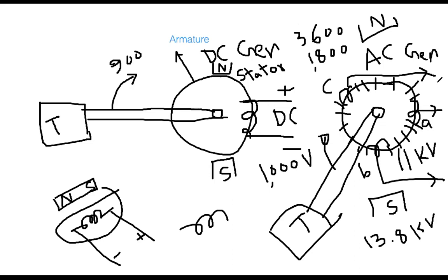And then, I mean, the next question is how you will take the power from here, because you see that these things are moving. You can argue that, okay, I can take power with the help of slip rings and brushes. That is also true. There is no problem. But the problem is that because this body will rotate, during rotation or after a long-term rotation, maybe not immediately, maybe 1 year later, 2 years later, this insulation might be lost.